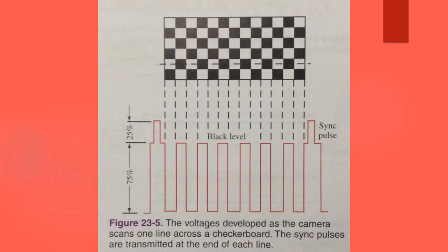Composite video signals. All video signals are formed in the same way so that a television can be used in any geographic area. These standards are set by the FCC and are used by all TV broadcasting stations. The television signals received by TVs contain picture, video, and sound, aural information. The video information is an AM signal. The audio information is an FM signal.